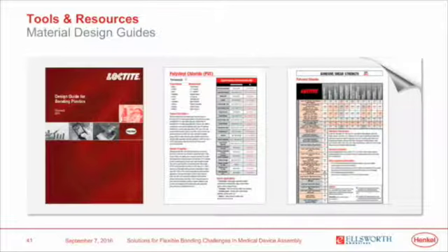On the right side of the screen, you'll actually see the bonding data. So each chapter for each of these plastics also includes detailed bonding data. And in this case, we not only took the standard virgin resin, being PVC, but we also looked at it from a variety of different perspectives, looking at different treatments of the plastic, different additives to the plastic, and then tested it with a wide range of adhesives to give you an idea of how bondable that material is over a wide range of adhesives. So again, this is a resource that is available to you for both plastics, as you see here with the red guide, elastomers, as you saw on the previous screen, as well as metals.